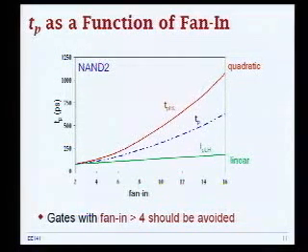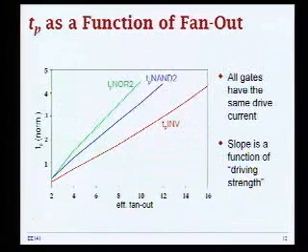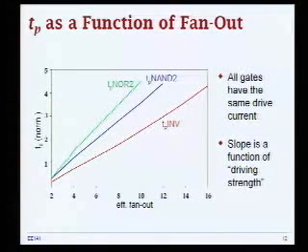So in the next couple of illustrations, we will see some of the techniques we can use to efficiently implement gates with large fan-ins. This is another thing over here. What happens if you increase the fan-out? Let's say we keep the fan-in the same. What you're going to end up with is basically only an increase in your load capacitance.